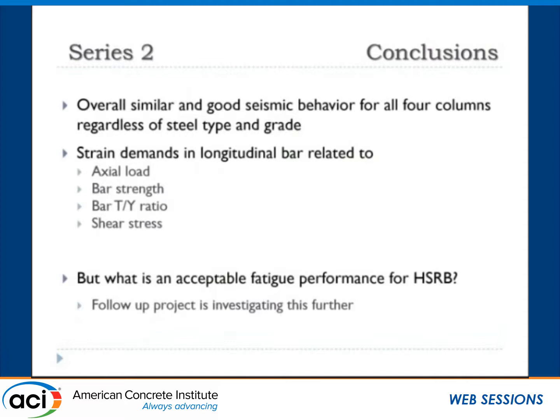Now, Series 2 conclusions: overall similar and good seismic behavior for all the columns. We looked at the strain demands, and they have a lot of variables that are affecting them. And then we got to the point of asking ourselves, well, there are big differences here and there, but what is really an acceptable number? What is an acceptable fatigue performance of these bars? What do they need to sustain to give us the same safety margins in our members, in our structures? And that is a follow-up project that I'll talk a little bit about that we just started.